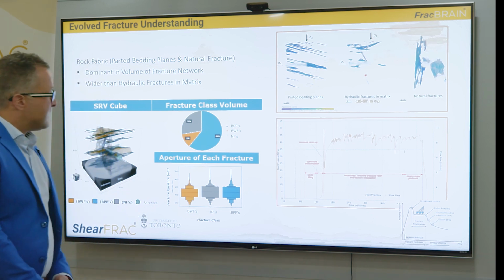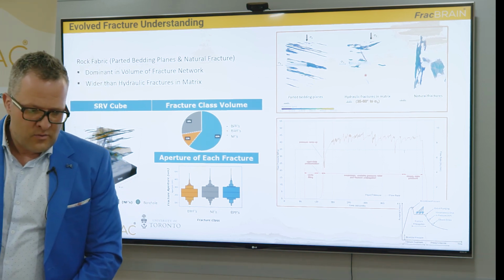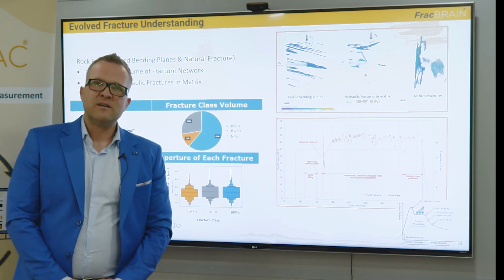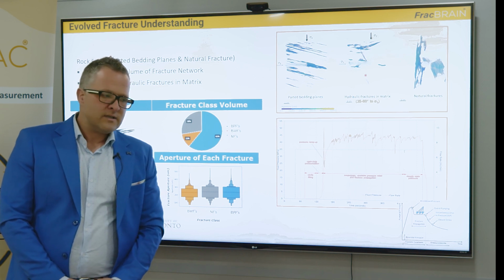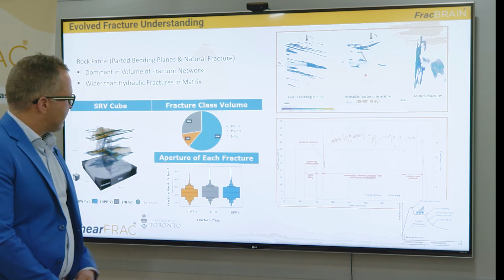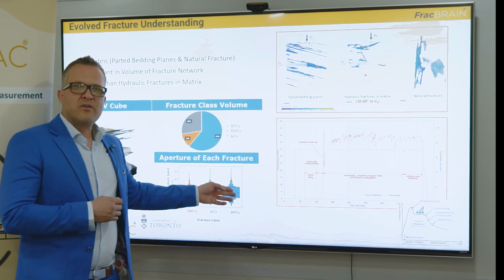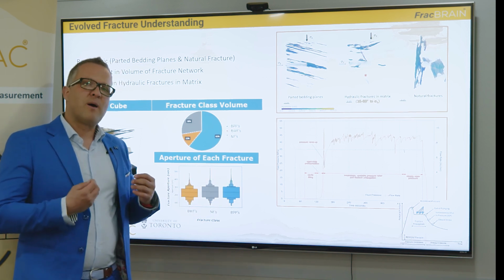One limitation of this test is we were not allowed to pump proppant in a $30 million machine at those pressures at surface. So we have to infer, based on the size of the aperture generated, that proppant could transport along the bedding plane and it would be propped open for flow.